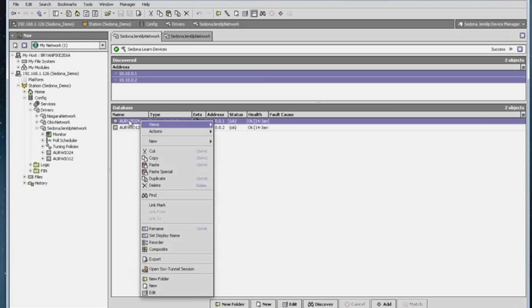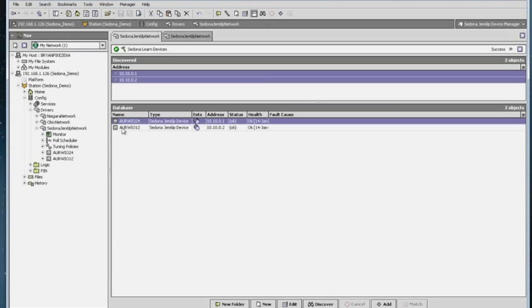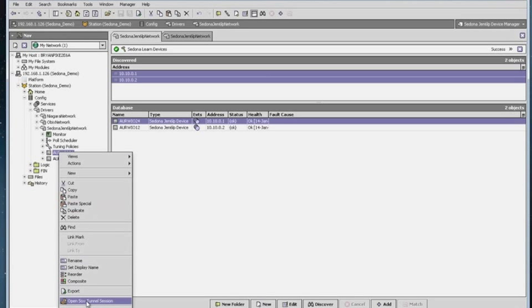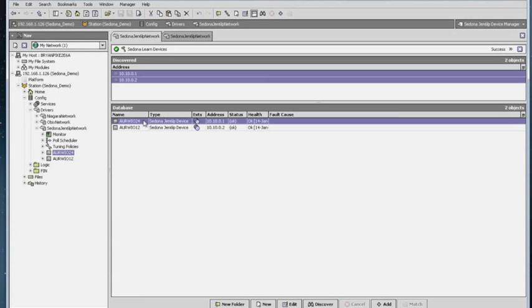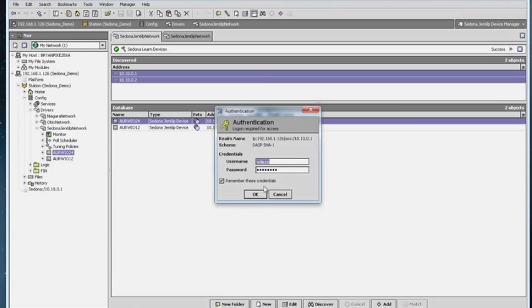So let's right-click on your controller here, and you'll see the Open SOX Tunnel session. If you had not dropped in the SOX Tunnel service, this would not be available to you. Now you can enter into a SOX Tunnel session from this location or from your tree by doing the same thing. So you've got Open SOX in both locations. So from here, we'll just open the session.